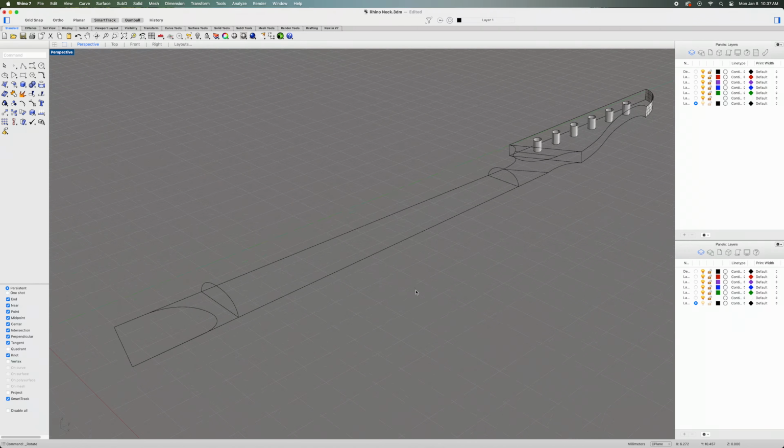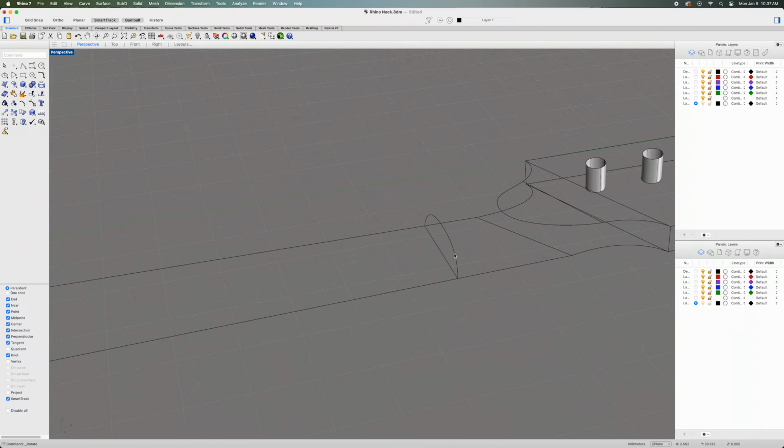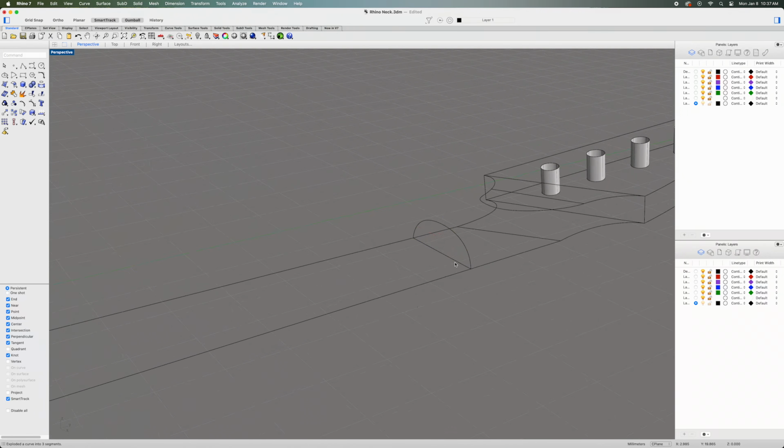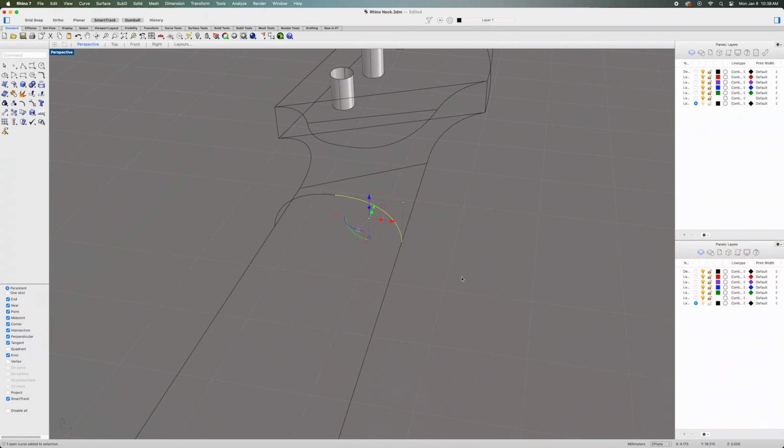And then what I have to do, this is where things get a little bit complicated. But in order for a contour to work as efficiently as possible, and to look correct, you need to build out the structure. So the more structure you have for the surface to adhere to, the better. So what I have to do is break apart these lines and then split them into segments. And I'm going to split each of these curves into a total of 8 segments.